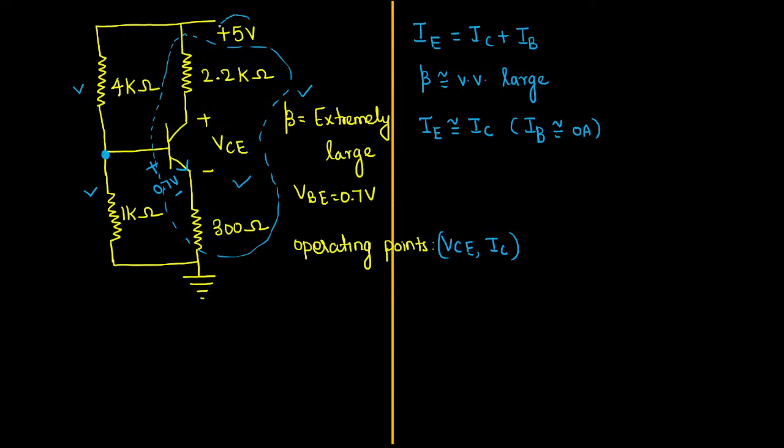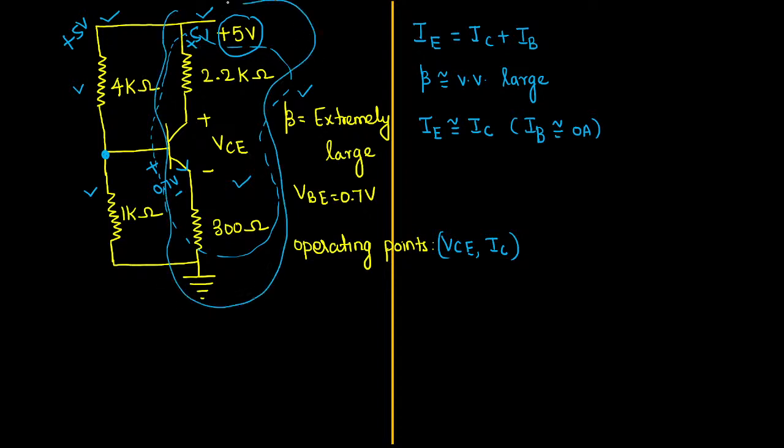See there. On the top, the supply voltage is 5. It is common for both the transistor and the base terminal. So here I am breaking this into two. I am keeping 5 volts here also and 5 volts here also. This entire zone will be treated as a load, so I am removing it while applying Thevenin's theorem. The moment you apply Thevenin's theorem from the base terminal, I am just Thevenizing the circuit.